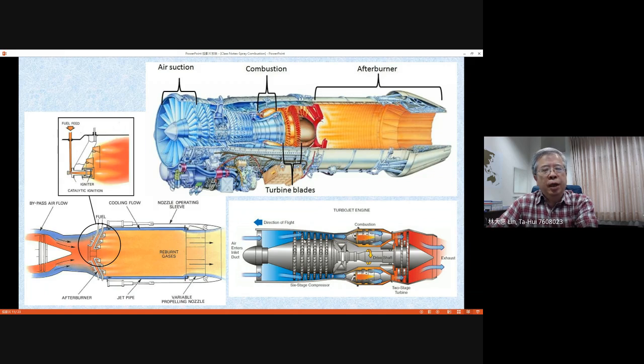If you look at the suction of air into the whole gas turbine, as you remember, we split the airstream into the so-called primary air and secondary air. Primary air goes into the combustors to complete combustion, but the secondary air moves along the annular port and flows into the combustor through the liner to cool down the surface of the combustor, and later moves downstream.